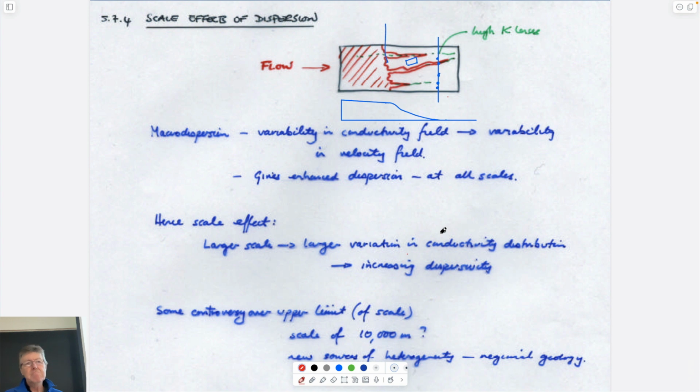and you're using clay, the surrounding clays as the barrier for stuff escaping, then measuring the dispersion in a clay sample in the lab is good. If you want to measure dispersivity in a granular or a sandy material or a silty material like at Borden, it's not very good. And the reason is, one, it doesn't sample things very well. It doesn't sample the heterogeneity, which is important as you get to field scale. And so if you're designing at field scale, you'd want to do a test at field scale that samples that.